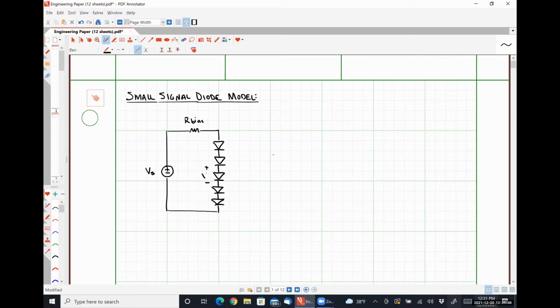All of these diodes will be identical so that they will all have a voltage drop of VD over them. They will all be carrying the same current, ID, and let's say that the sum of those 5 voltage drops, V out, in this case, is simply 5 VD.